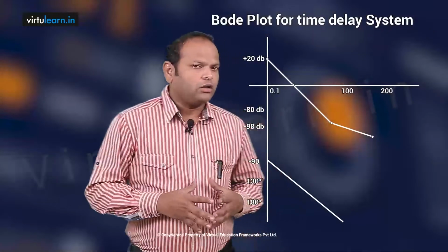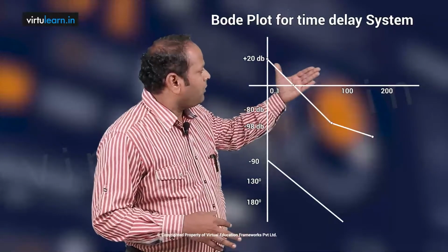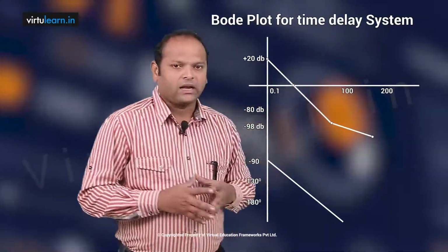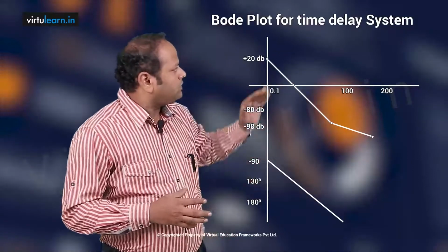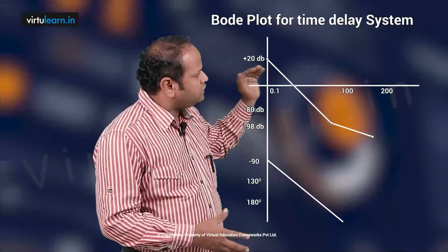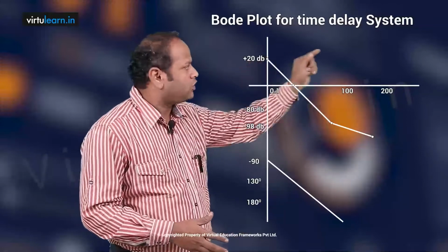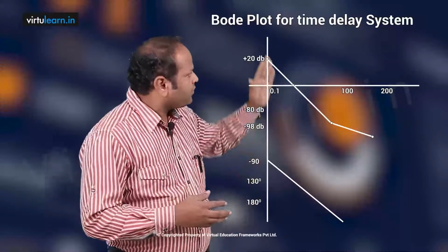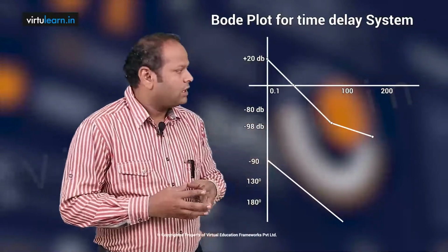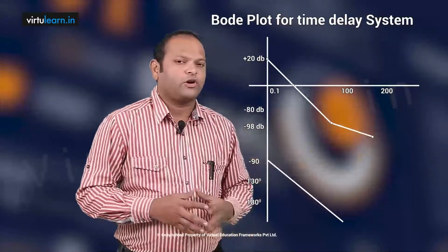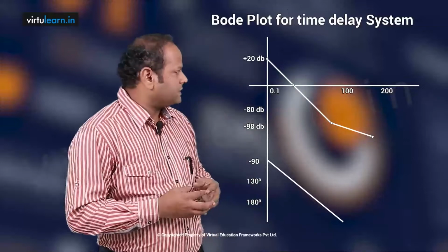While having all the data, which is the magnitude table and phase angle table, we can plot the Bode plot. So this is the semi-log graph sheet. Then I can choose the proper frequencies over the top of it. On the left side I can take the range of M dB values, and on the right side I can take the corresponding phase angle values in degrees.